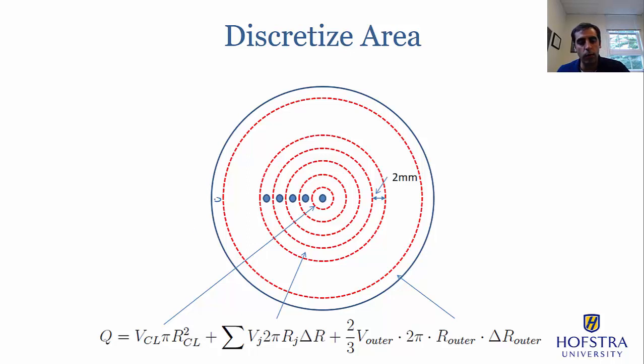So if I had one more point right at the end here, now, because the probe has some thickness, I can't actually get to the wall. And so I know the no-slip boundary condition would mean that exactly at the wall, I should have 0 speed, or let's just write 0 meters per second here. But I'll never measure that because I can never get exactly to the wall with my sensor.